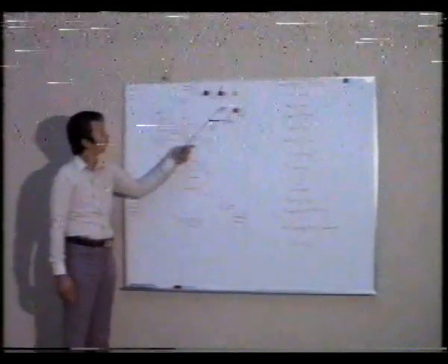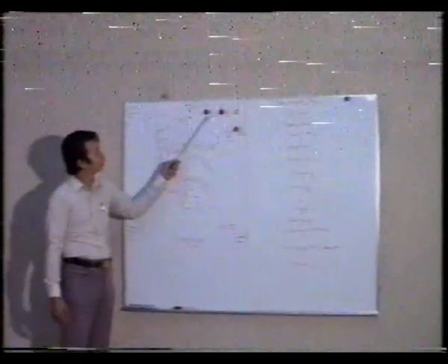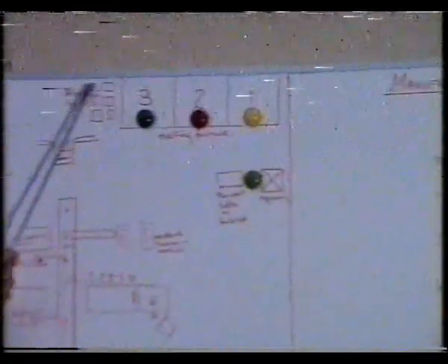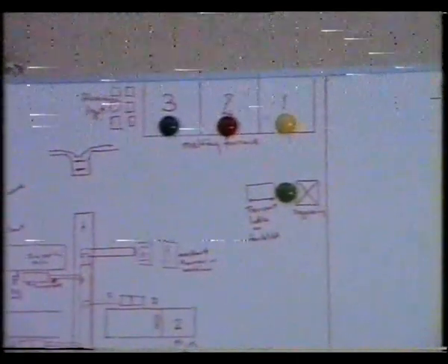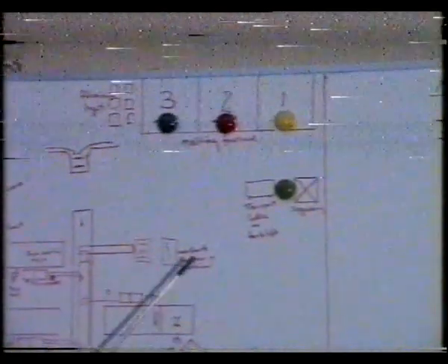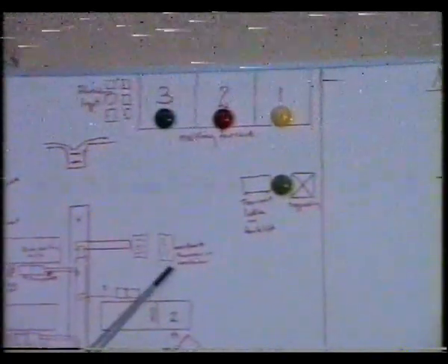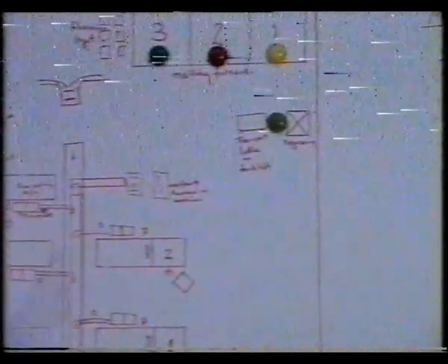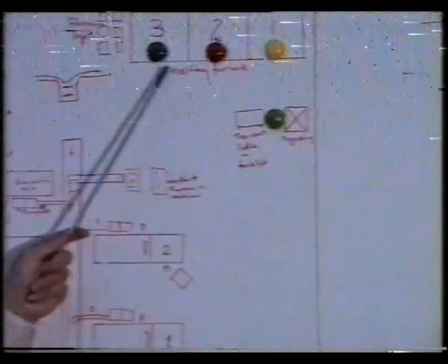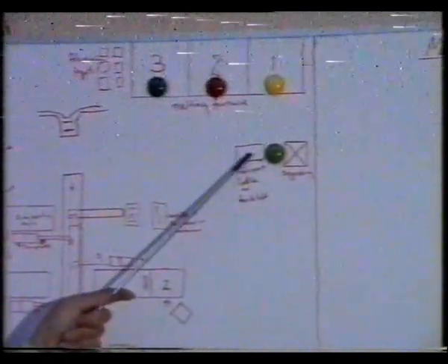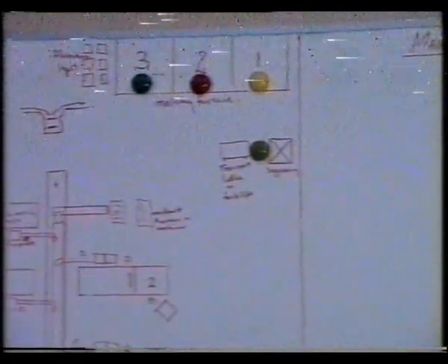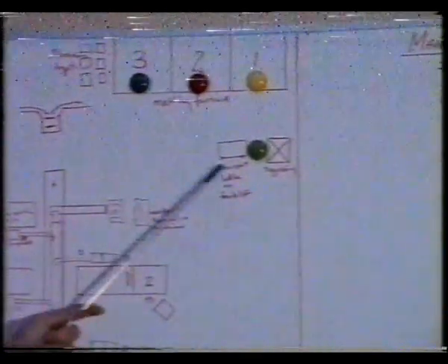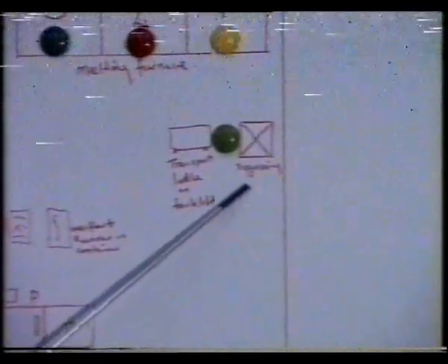And coming to our layout, we have 3 melting furnaces over here, each of them 800 kg. You can see over here is our aluminum ingots. Here is the return from all the machines with the runners and overflows. We put them to melt. After melting, we have a forklift attached to a transport crucible. We bring it over here, and here we do our degassing.